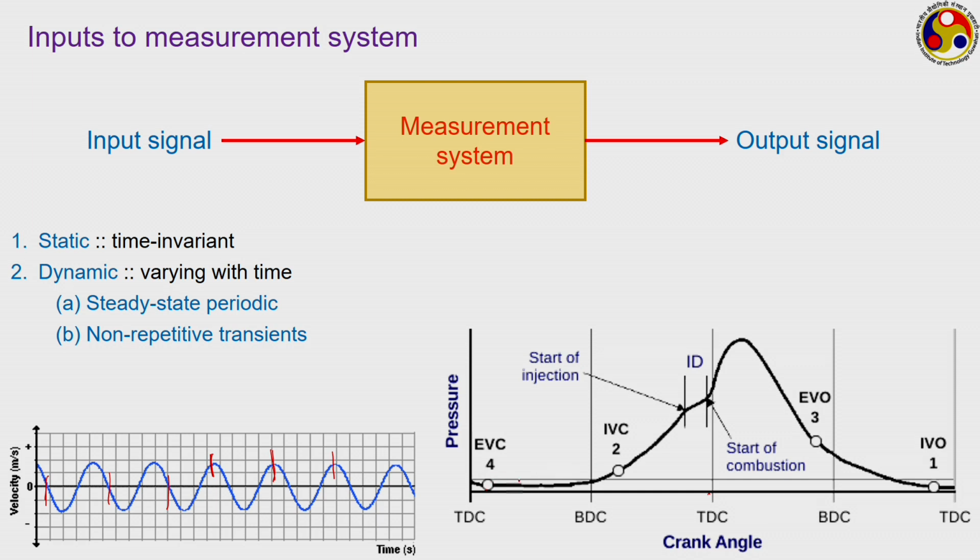Pressure initially is almost flat during the first stroke, that is during its movement from top dead center towards the bottom dead center, during which the injection is taking place, or I should say the supply of the fuel. During this first stage, pressure remains quite close to the atmospheric pressure.